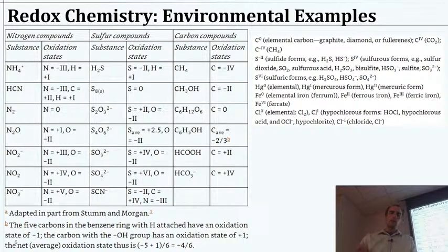And what we would find is if we're going all the way from sulfide, it takes 8 electrons to get sulfide to sulfate, and therefore it's going to consume 8 molecules of chlorine. Because when we look at that, we'll see each free chlorine is essentially doing a 1 electron transfer. Okay.